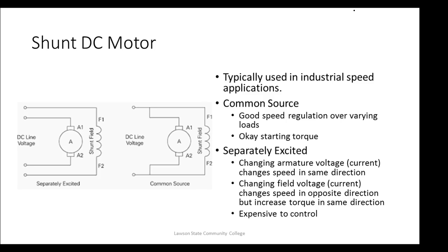Now, what would be the advantage of this guy? The amount of torque the motor generates depends on how much current you have in the armature, or the strength of the armature field repelling or attracting the strength of the other field. With a permanent magnet, you're controlling only one field, the strength of the armature field.